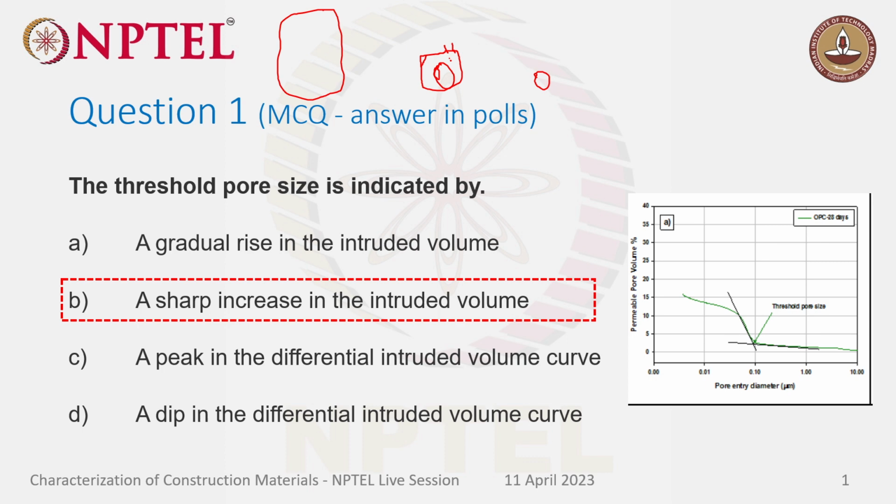And if you're taking sulfate attack samples, sulfate attack will happen mostly on the outer side. So in that case, you have to take samples from there, and some consider this to be a sulfate attack sample. So mostly we'll take samples from here, and we'll do MIP here. Here the pore structure will be different. And if you take an unaffected area, not much gypsum will be formed, and the pore structure will be more intact here than there, where it might not be intact. Understand, no?